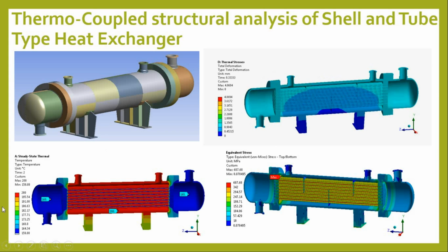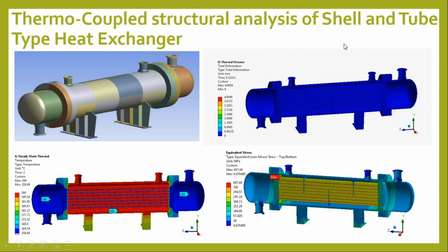Once your thermal loads are applied, there are also some additional pressures, like the shell and tube side pressure. That's why it is called thermocoupled structural analysis. So first you need to follow the thermal analysis, then you need to couple that with the structural analysis. In structural you can apply pressure loads. Okay,